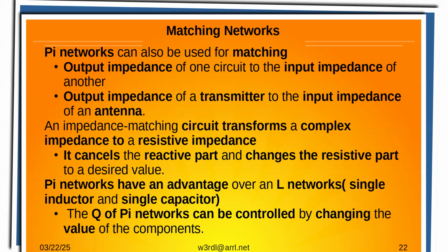So if you have, say, your antenna is a dipole and it's up high enough, it's 75 ohms, which is typical, but there's some reactance to it. It's not pure 50 ohms, or 75, but you want to match that to your 50 ohm transmitter.